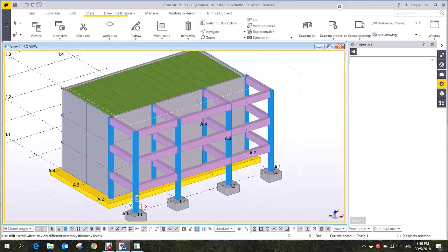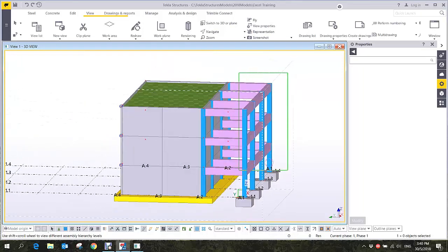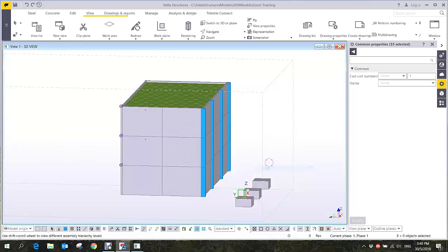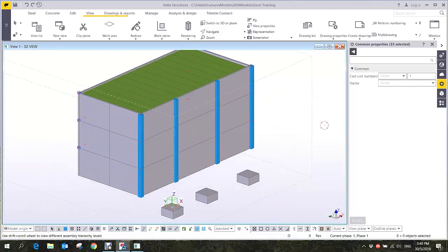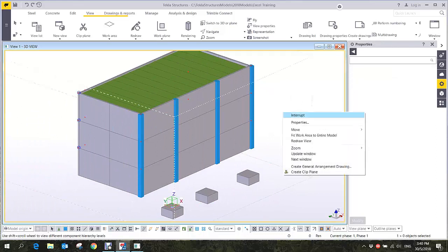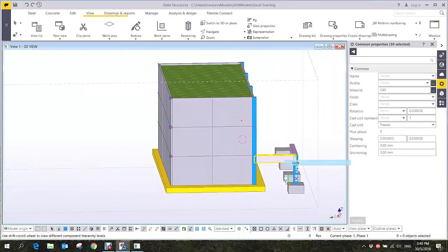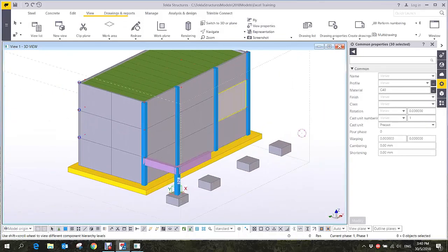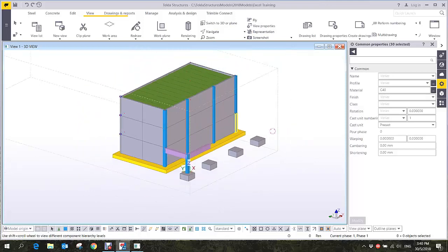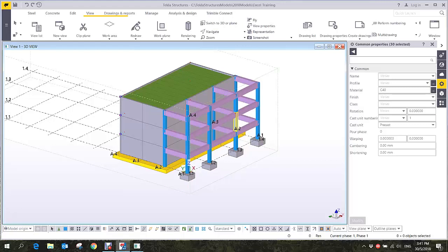Again, there are two types of hide. Look, if I select, I don't know, in version 18 it's the same. Right click and then hide. So no need to press the shift key. Actually, redraw. Again, select, hide. Okay, no need to press the shift key. Everything will be hidden. Last time, when you don't press the shift key, there will be a line. I mean, the center line is still there, but now it's okay. Right? So, redraw.